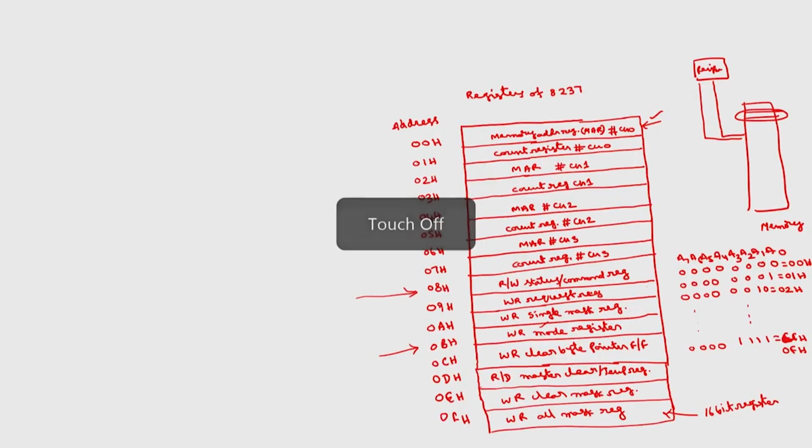So, I want to store the starting address in channel 3. This is the channel 3 memory address, and the count register I have to load with 03FFH, because 1K is 03FFH.